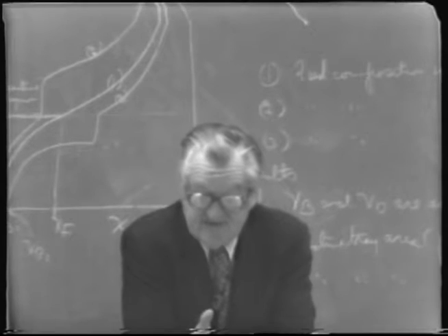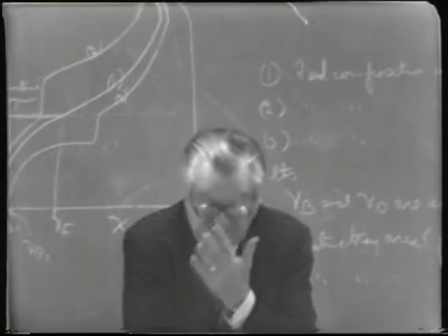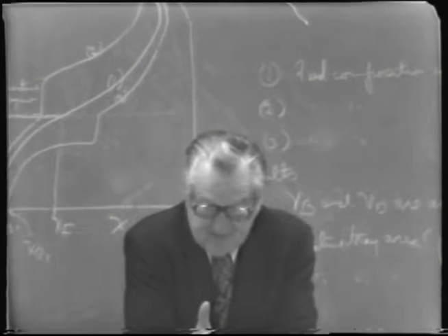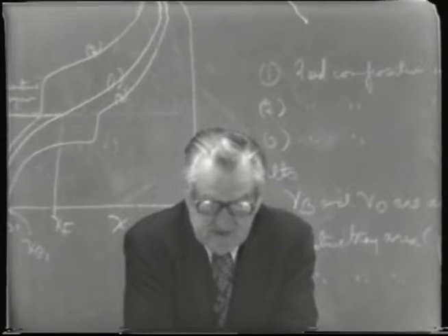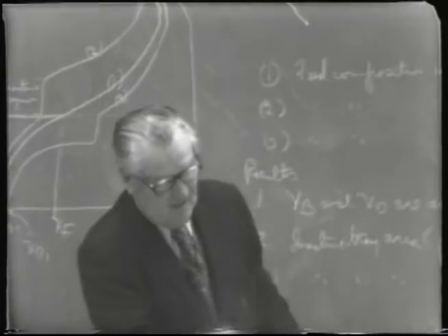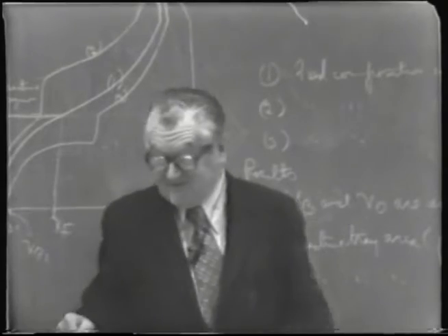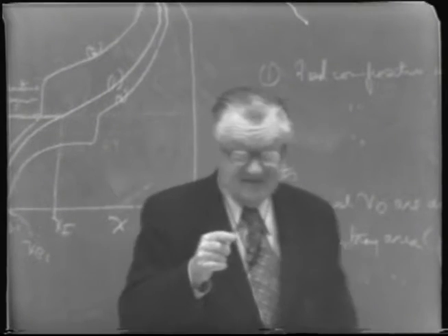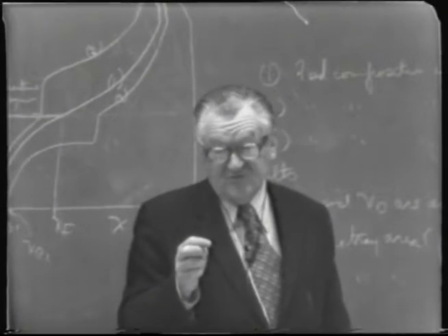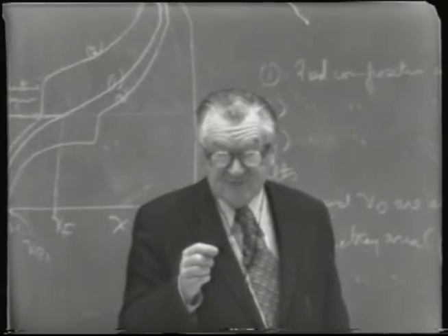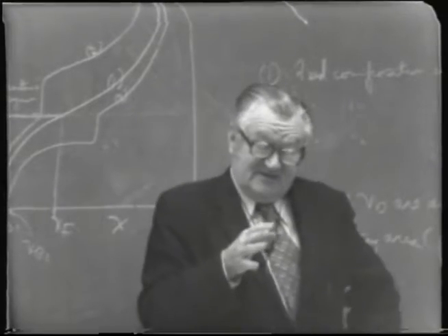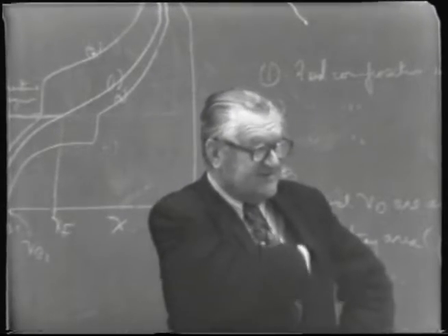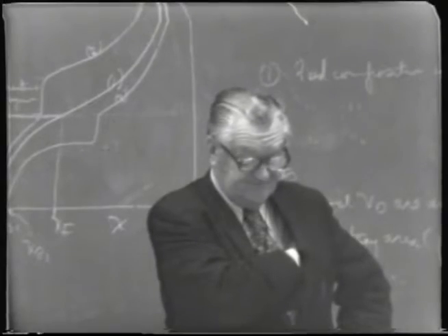Well, maybe I didn't say it very clearly, but what I said is that many of the times our stripping sections are relatively low efficiency as far as plates are concerned, so that if they have 20 trays, they only have maybe 10 ideal trays. Although this will get you down to a pretty low level if you try to plot it on a curve like we have, when you try to get down to as low as 2 to 3 or 4 hundredths of a percent alcohol by volume, it takes a lot of steps right down near the bottom to get it down to that low value.